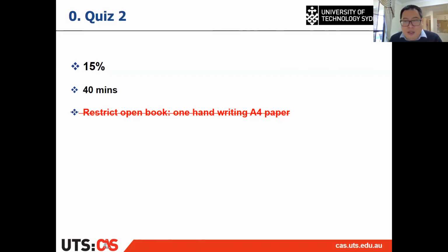Another example is if I'm asking you to assess the stability of a linear continuous time system. There are several steps. First step is get A. You answer that the stability of the system only depends on A, and you can also answer the criteria. For example, if all the eigenvalues are negative or have negative real parts, then that is stable. So you write down that.